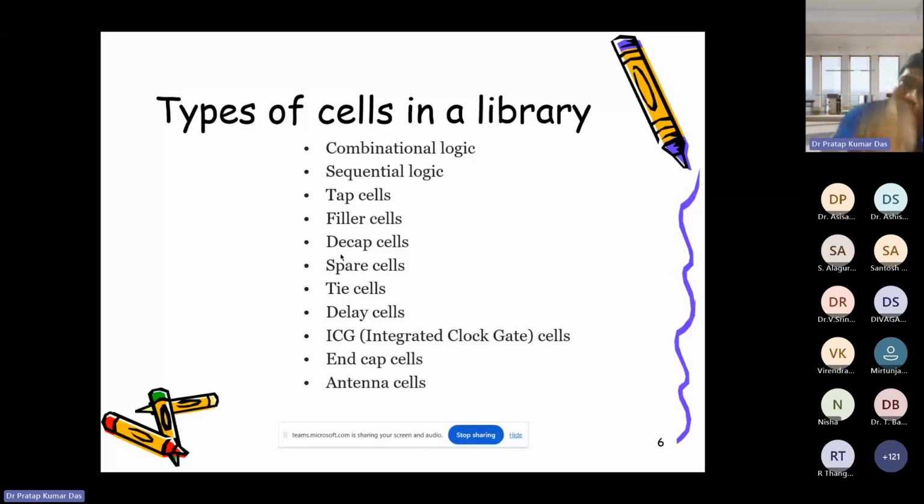If you connect to the diffusion, the damage is much less. But if you connect to the gate, because it's CMOS logic, it becomes very bad. That's why you need these tie cells. These tie cells are, by construction, connecting the output to 0 or 1.